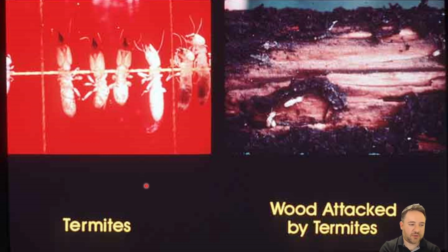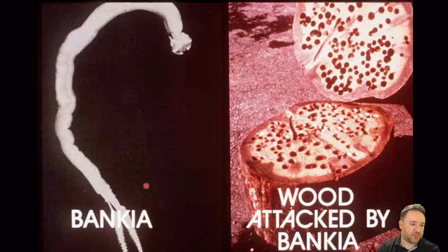We want to keep it away from being attacked by termites and other insects and worms and stuff that will attack the wood. A lot of that will be in detailing of the envelope, which is not usually our responsibility, but to keep the infestation out. But there are also, I think, wood treatments that can prevent termites from liking them. Here's another potential pest of wood and what it's done to a living tree, called Bankia.